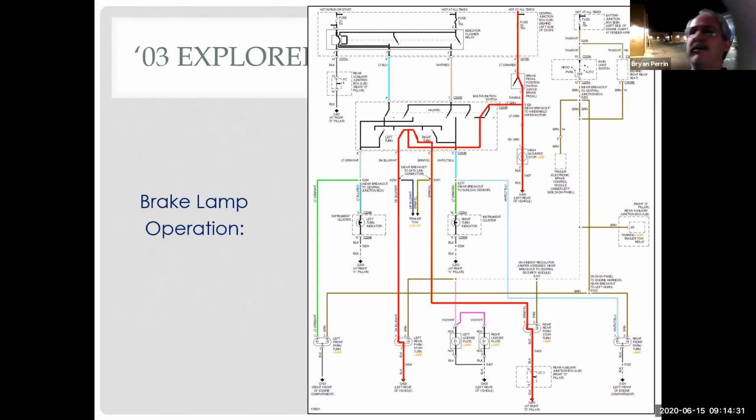So here's our wiring schematic. I've got 4 wiring schematics, and I highlighted in red where the current flows in each of these positions. What we want to look at is what they have in common. Obviously what's going on is we have circuits that are shorted together, because my license plate lights aren't supposed to flash with my turn signals, right? So I have to look for some place that everything shares.